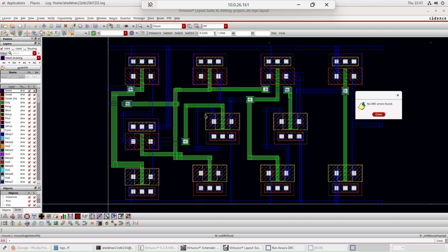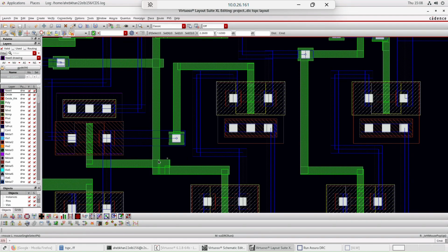Okay, so in design rule checks, when I had created the layout, there were several errors when you run the DRC. All right, so you have to read them and understand that, okay, it requires poly to poly spacing greater than 0.1 micrometer, it requires metal to metal area less than 0.7, something like that. So you have to read it and sometimes you have to make changes accordingly. All right. Now, at the moment, we are not looking forward very much at optimizing our layout, reducing the areas, reducing the wiring, because all of this that you see here creates delay.